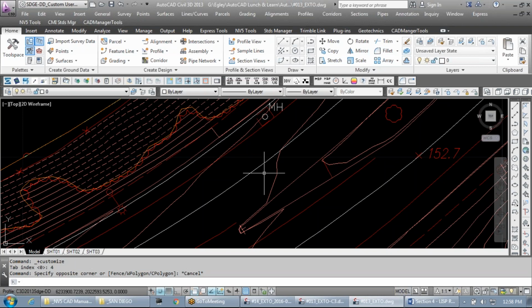Vic? So how do you control the text height for different viewports with different scales on the same sheet? Good question. So there's a couple different ways. In those cases, annotative text may be exactly what you want to use, right? If it's something that isn't necessarily dependent on that same callout, there's cases where, yeah, I don't want to have to retype that 2 different times at a different scale. I want that text. Yeah, by all means, use annotative text. But sometimes, hey, it may be better to have separate text on different layers and different sizes. So it kind of depends on what you're after.